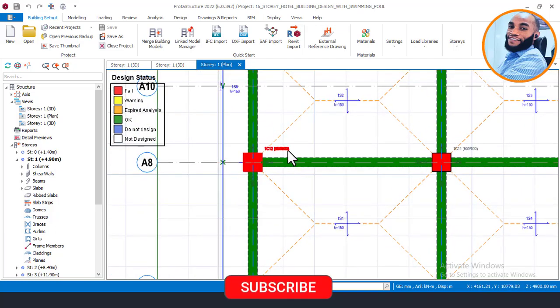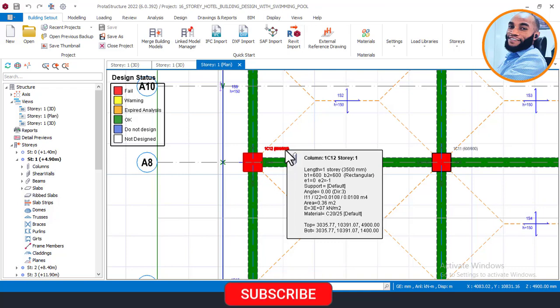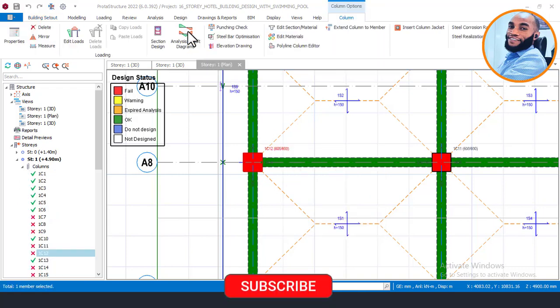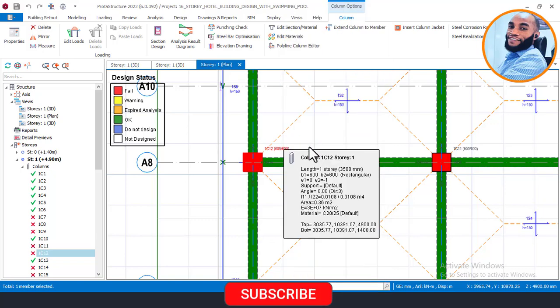To check why your column is failing, click on the column, right click, and then click on the place that says section design. Once you click on the column and right click, you will see section design here. I'll click on this, and it will open up the column dialog for interactive design. Let me just hold on for that to come up.